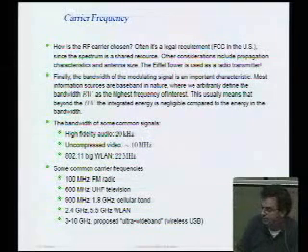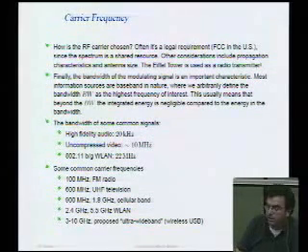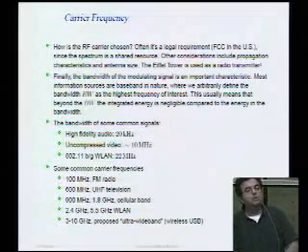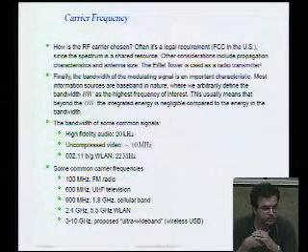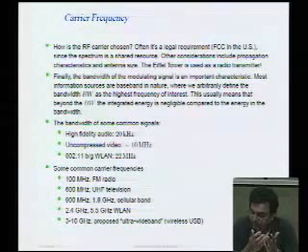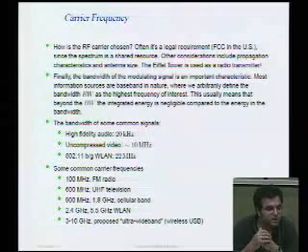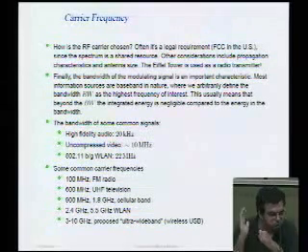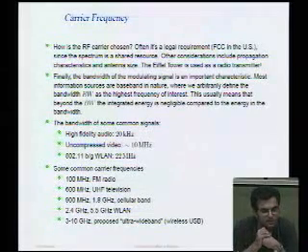Now the other constraint that we already touched upon a little bit is bandwidth. So depending on what kind of information you're transmitting, you have to also take into account how much bandwidth you're going to occupy. So in other words, if I'm going to transmit voice at 1 gigahertz, I may only need about 10 kilohertz of bandwidth. Maybe 100 kilohertz if I want to transmit FM.